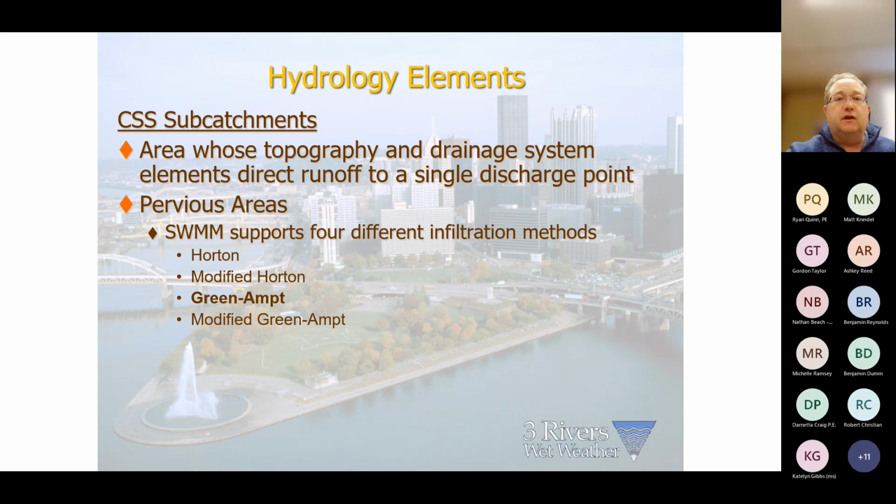The infiltration really is, you're only going to see that impact on really, really intense storms. So if you're seeing a difference on your smaller events, it's not your infiltration into the soil that's going to make that correction. That's going to be your impervious parameters. So I capture pretty much what you're saying there, Sam.